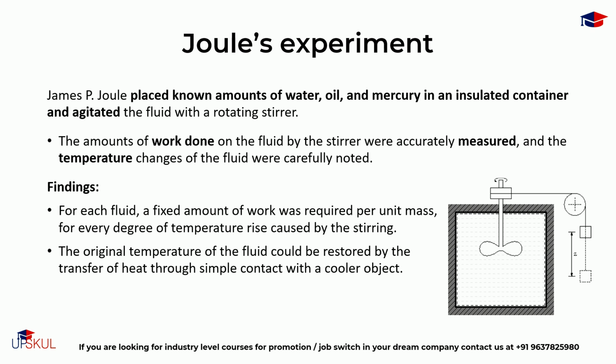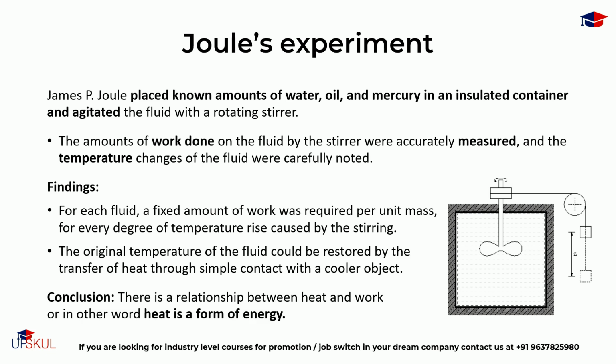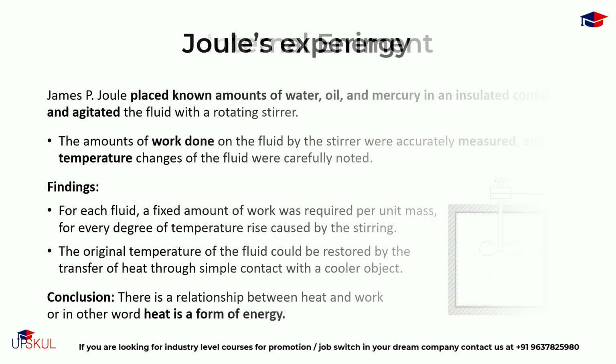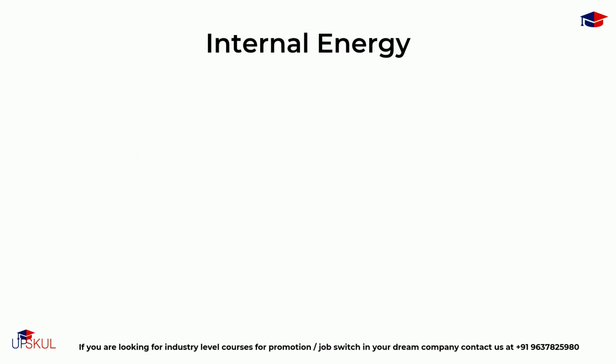From this experiment, we can conclude that there is a relationship between heat and work, or in other words, heat is a form of energy. Through Joule's experiment, we need to know what happens to energy between the time it is added to water as work and the time it is extracted as heat. Logic suggests that this energy is contained in the water in another form, which is called internal energy.